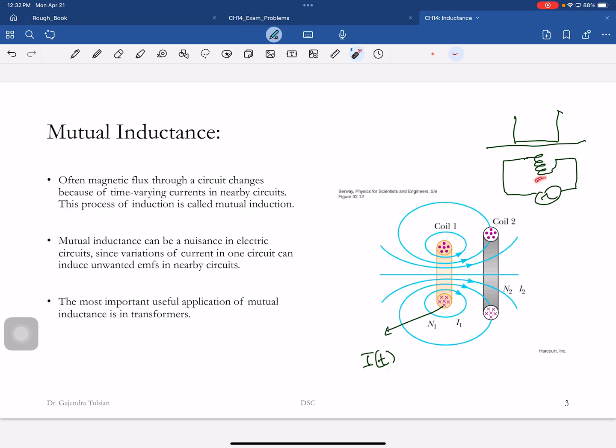So these inductive stoves are 90% efficient. A gas stove is about 40% efficient. That is, of the heat generated by burning gas, only 40% goes into heating your food. An electric stove is only about 70% efficient, because in an electric stove there's a coil underneath which is heating the glass top, which is heating the pot. But the inductive coil is directly heating the pot.